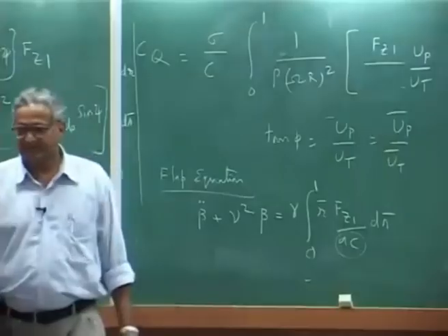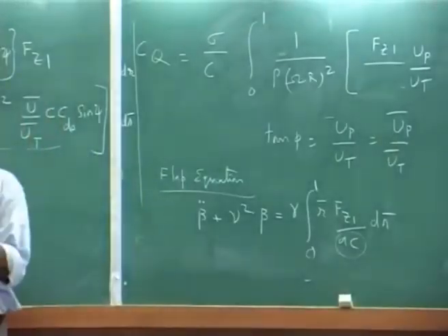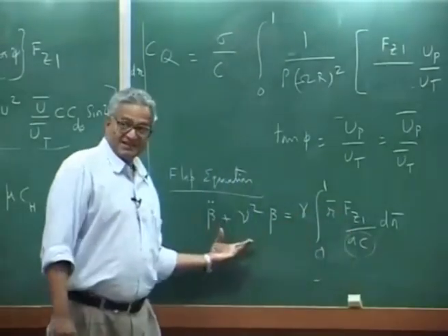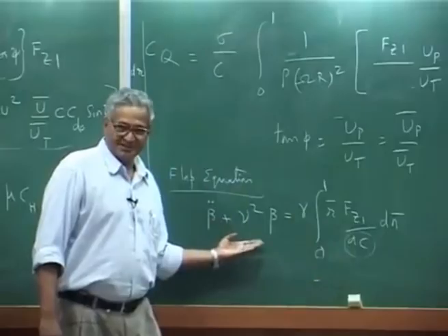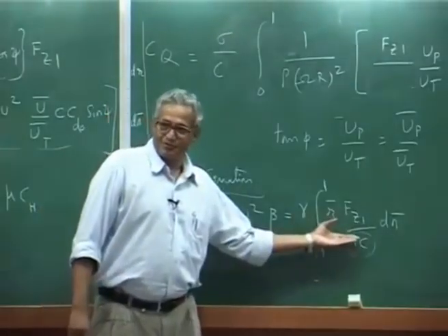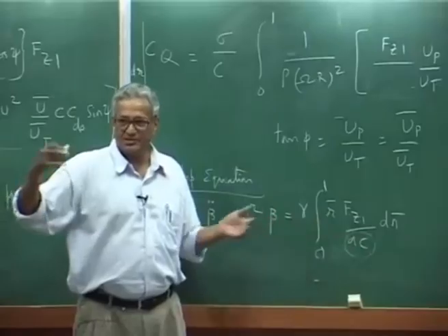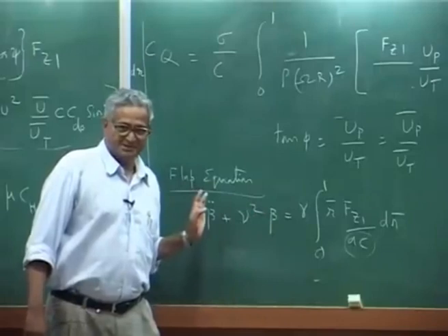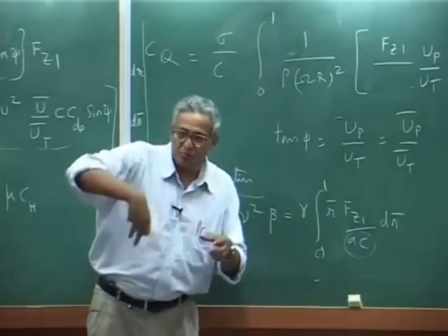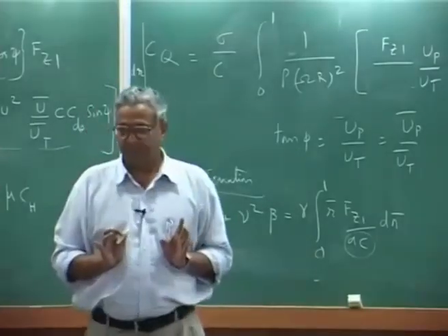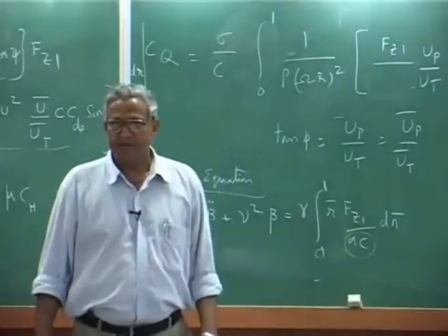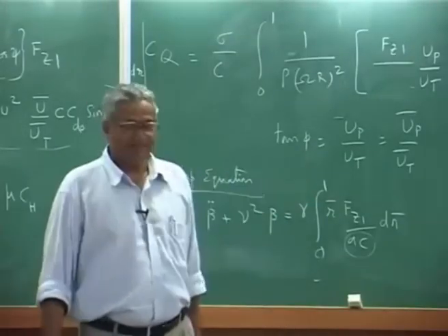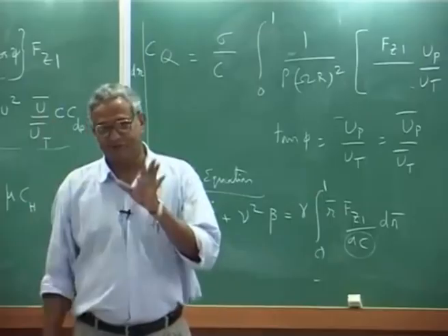When you do one cycle, this is basically the aerodynamic force, and this particular side is the inertia term. The aerodynamic force, because in dynamical equations you have external force and centrifugal force also, that is why I said this is the inertia term. Since you assume periodic motion, you will find that the total work done by this force in going around is 0.